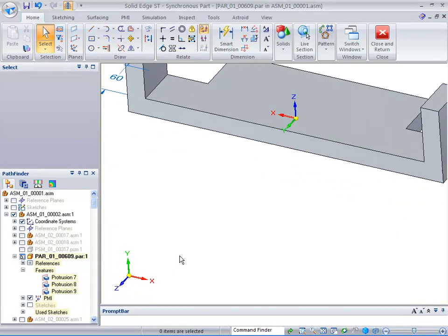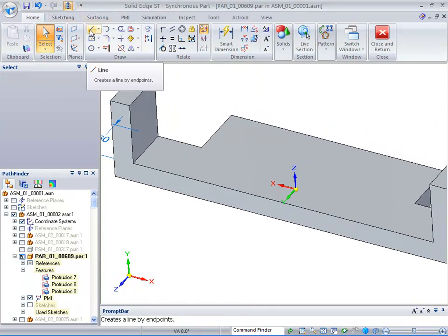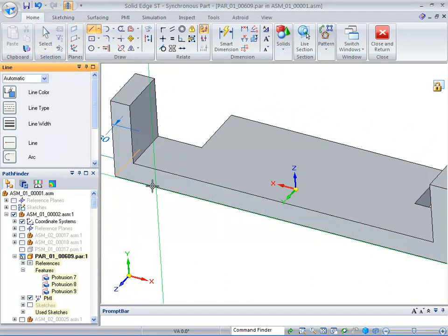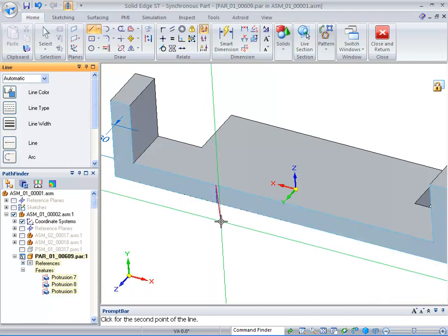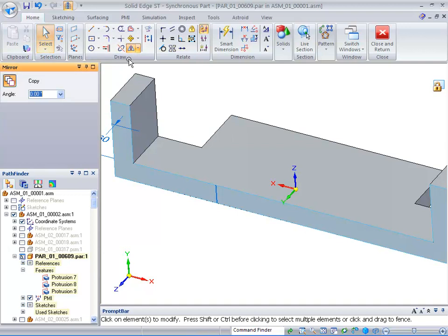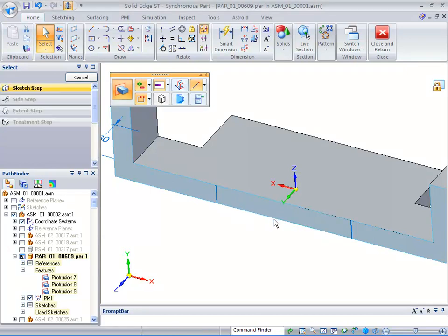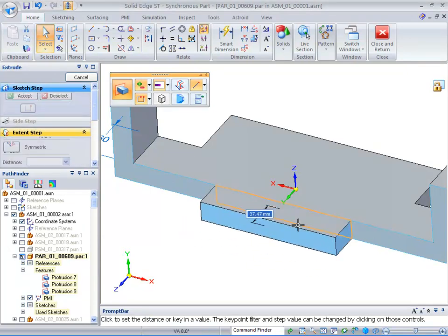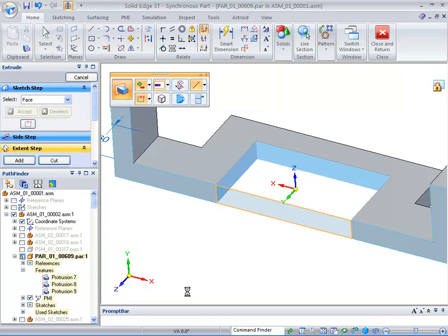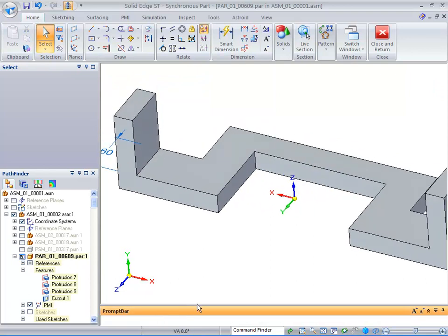Roll the part over, same thing, create a line now on the bottom face, lock onto the plane. You want to come inside of this edge that you just created, create a vertical line, same thing, do the mirror, select the sketch, pick the Z, and very quickly you can create those regions. Again, just drag up to create something that looks like this.